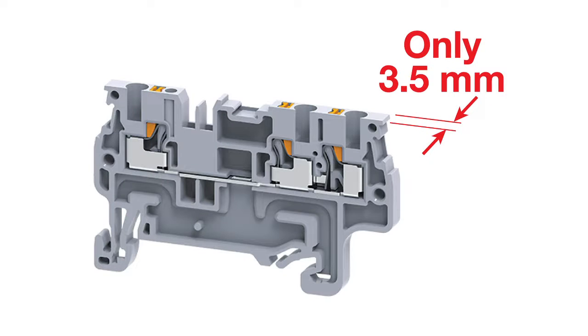Furthermore, another benefit is the high density wiring that comes not so much from the connection itself, how I connect a wire into a terminal. It's really the unique design of these terminal blocks that allows them to be designed very thin compared to screw terminal blocks. A push-in design actually allows a size reduction of about 30% of a terminal block size compared to screw technology.